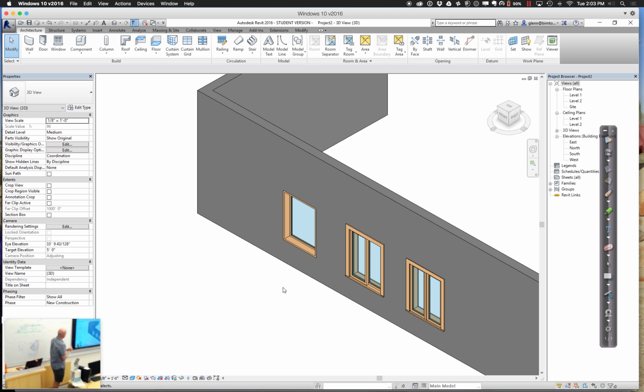In terms of just thinking about them, let's think about different perspectives. In terms of how much, for example, view they're allowing, are they similar or dissimilar? Look at that. I'd give them a similar. There's a little blockage in the middle, but not too often. If it was a big window, they're pretty good on view. How about on daylighting? Is daylighting going to be pretty similar on those 3 windows? Yeah, they're all going to be pretty much the same. There's a little blockage because of that little part in the middle. But yeah, I'm not going to worry about that frame too much.